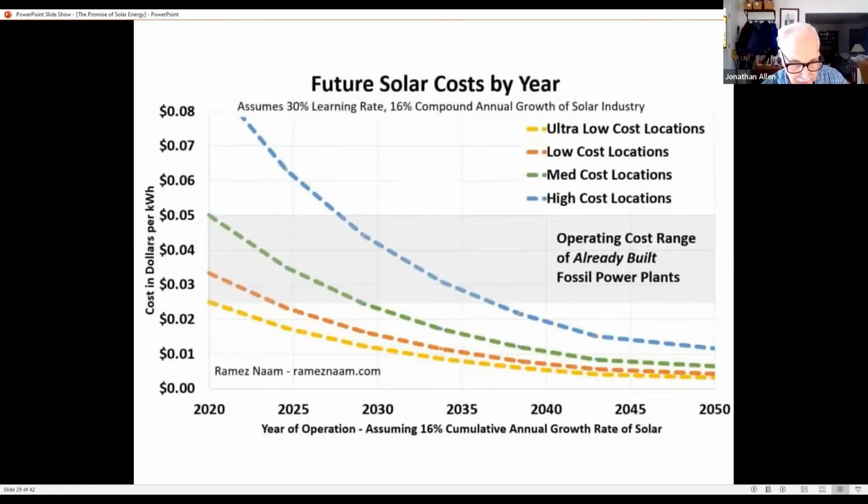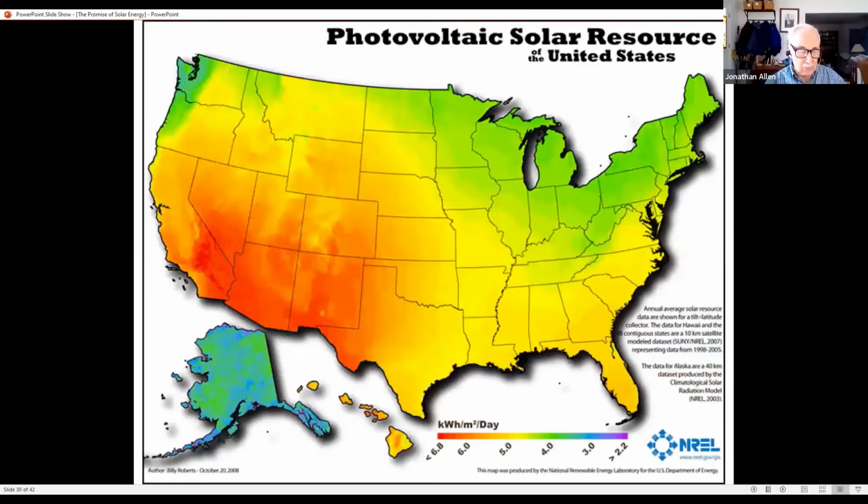Since sunlight affects output and hence payback times, these payback times and economics will vary with the location. So let's look here at our solar map. It shows the daily average over the year, average solar flux throughout the United States. And if you look around here in New Jersey, where we are, it's about 4.5. So on the average over the year, we see about 4.5, the equivalent of 4.5 hours of full sun each day. And some places are a lot better.